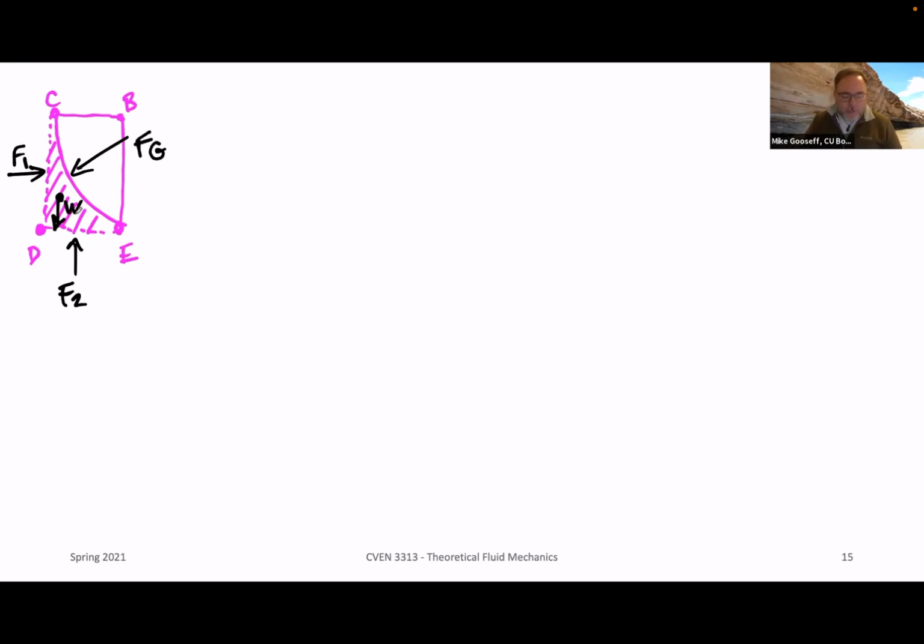Okay. So you might be wondering, wait a minute, why do we care about the weight if it's acting opposite the gate? The point will be that we still have to account for it within our system. We've created this little rectangular view of the world. It's fine if the weight acts in the opposite direction. We still need to take it into account when we figure out the balance of the pressure forces and the weight acting in the vertical direction, to know what vertical component is acting on the gate. Okay, so it may sound extraneous, but it'll be important.